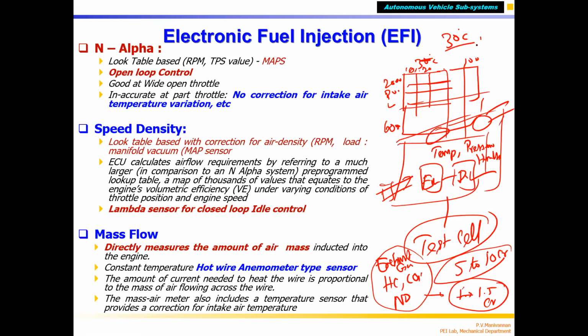So at 30 degree, 1 bar pressure, you create one table. So if you run your engine at 30 degree, when the vehicle is driven on the road, at 30 degree temperature, sea level in Chennai, early morning, in Vizag, or in Kochi, or in Bombay, sea level, correct? When temperature is around early morning, whatever map you created in the test cell for running the engine for 1 hour, 2 hours, each of these you filled, no? Take 5 minutes or so, that is valid.